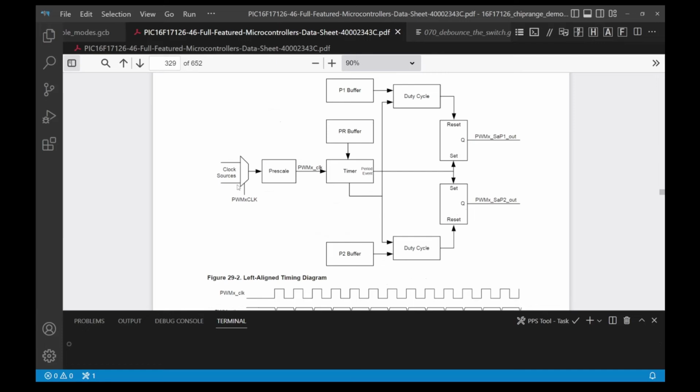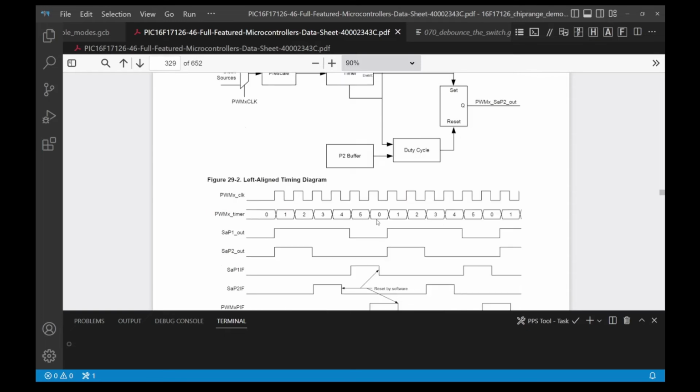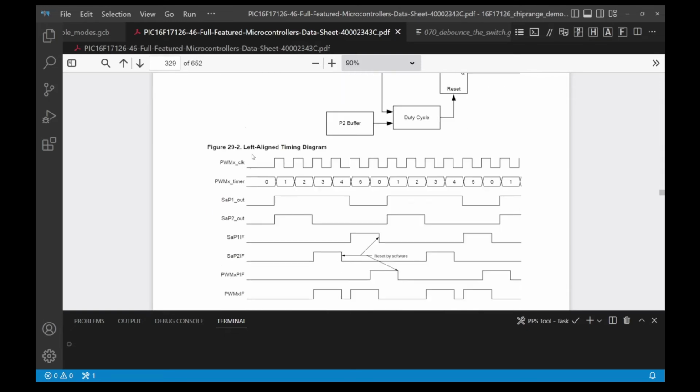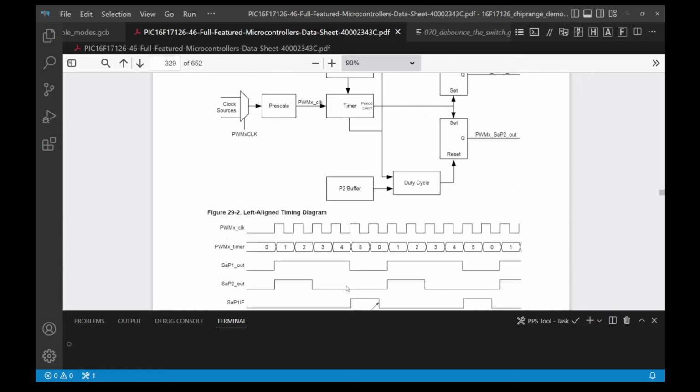I need to set up a clock source, a prescaler, a period event in PR and the PR buffer. I need to set up the duty cycle for one side, whether it's got a reset, and where my output is. So I'm going to have to set up 1, 2, 3, 4, 5, 6 different registers. Now, normally Great Cow BASIC in the background does all this for you, but these are new modules, and we don't really see the justification, because you need to do this on your own, because these are critical pieces of timing, because you can have extremely complicated and complex timing diagrams created.